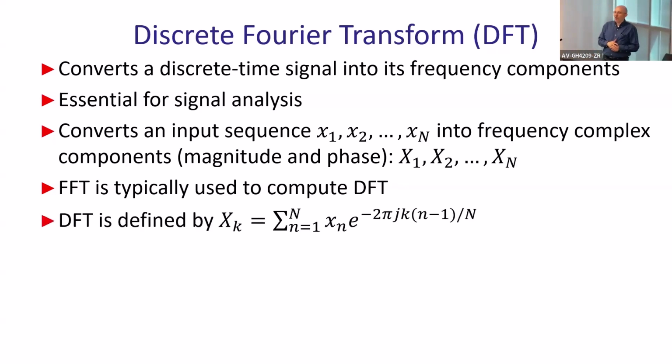And here is a complicated, complex formula for computing elements. And here's why that thing somehow is related to frequencies. Remember what is the exponent of something complex? Euler formula. What is the exponent of j theta? That's cosine theta plus j sine theta. Okay, this is what the exponent of j theta is. And here theta is a little bit more complicated. Okay, so theta here is minus 2 pi k (n minus 1) divided by all of these things. But you have j times something. It's some number, whatever that number is.